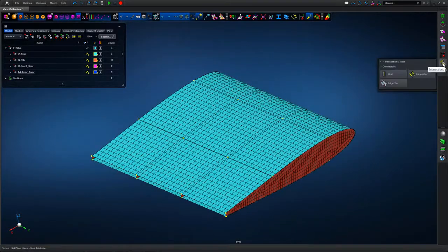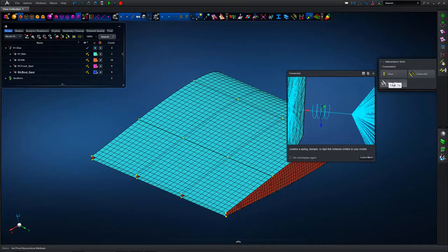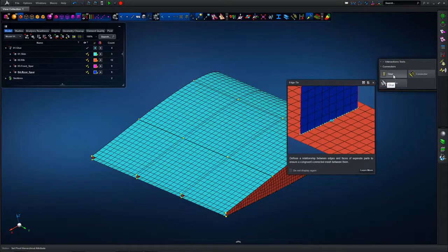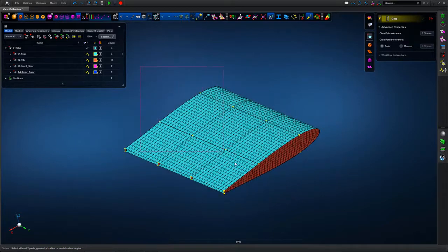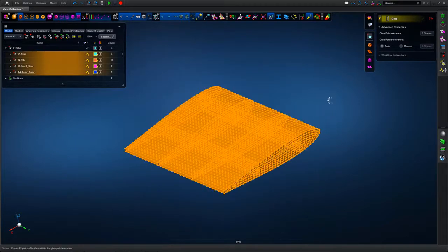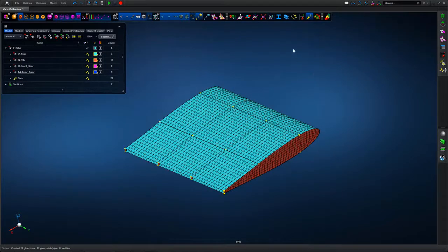And if we zoom in on the mesh definition, we can see there's no congruency again. So, the various interaction types we've got, showing some of the options here, but in this case we're going to use the glue contact. So we type in the glue pair tolerance, 5 millimeters in this case, so we want that tolerance to be bigger than the gaps within the models. And you can see just a global sweep over all the entities in the model.